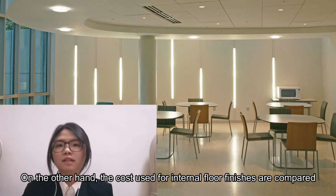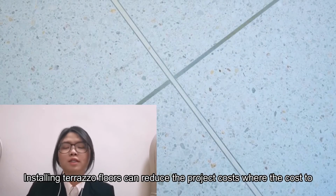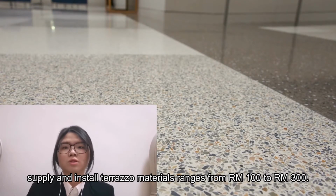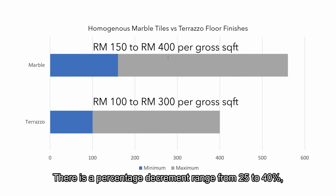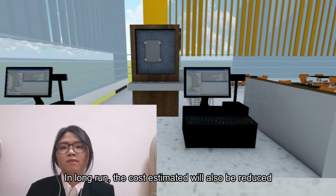On the other hand, the costs used for internal floor finishes are compared due to the change of materials as well. Installing terrazzo floors can reduce the project cost, where the cost to supply and install terrazzo materials ranges from 100 to 300 ringgit. It is a cheaper option compared to homogeneous marble tiles, which were used before greening the design, priced from 160 to 400 ringgit. There is a percentage decrement ranging from 20 to 40%, lower than that of homogeneous marble tile floor finishes.